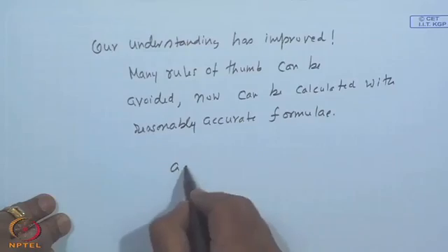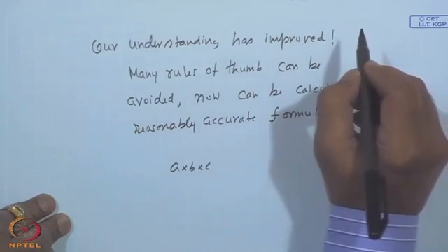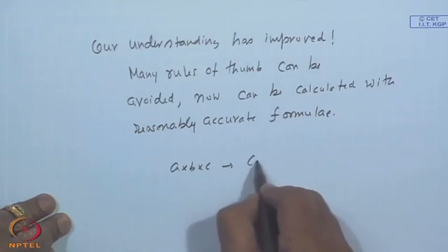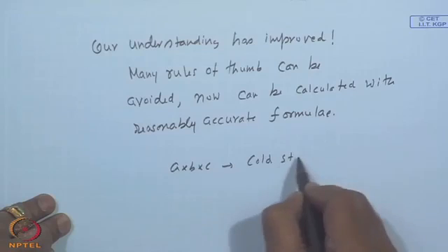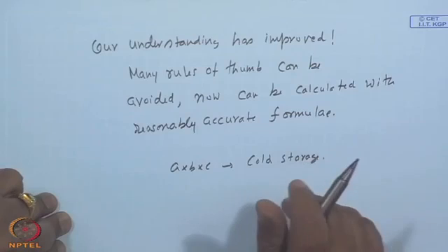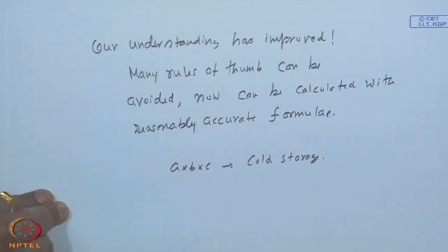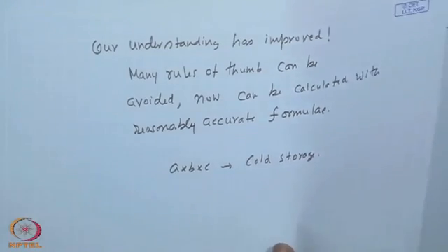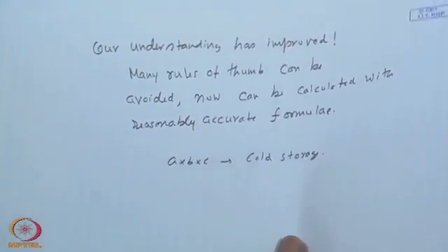Similarly, even if you consider a cold storage, you can choose a good orientation and A by B by C, or land area by the height ratio of a cold storage, such that it receives the minimum solar radiation, subject to certain constraints like a certain height. You can play with A, B and what direction it sees, facing south, north, east or something else, and this may help in reducing the heat load on the structure, similarly on any other building.